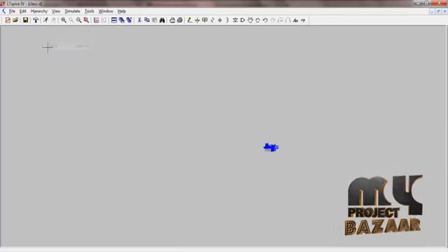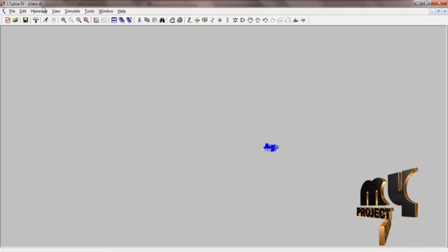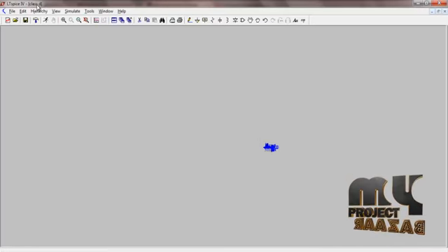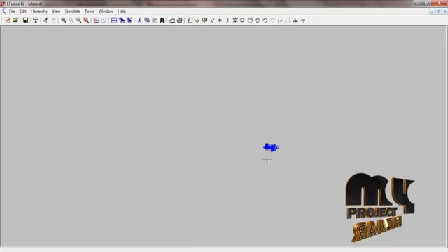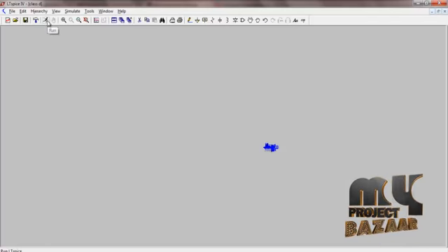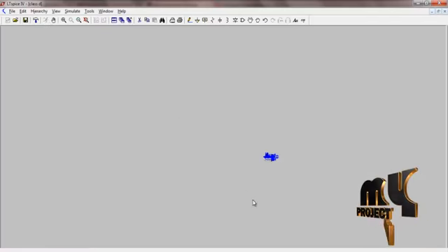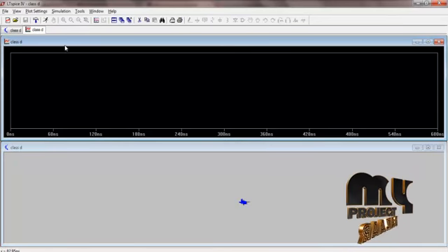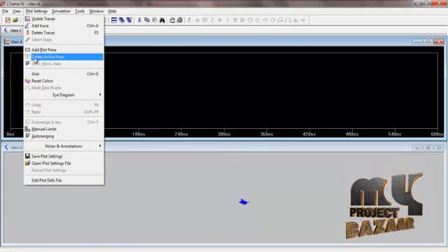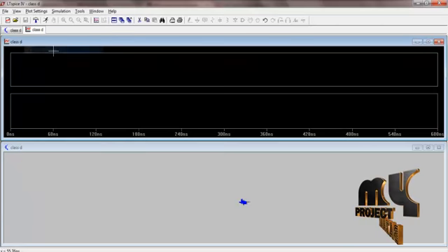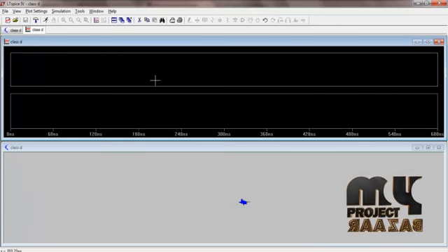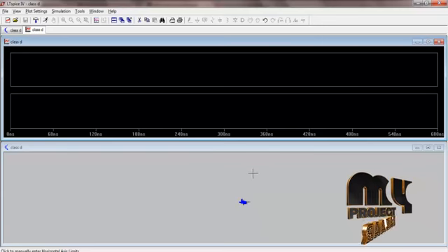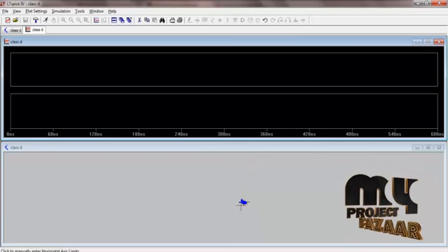Close this design. Our product is saved with the name Class D power amplifier. This is our design. In order to run this design, use the save and run option, and click run to run this product. This is an output waveform plot of our product. In order to add any plot, use the plot settings option to add a plot plane to add to this waveform side. Now we are going to see the input signal of our product.